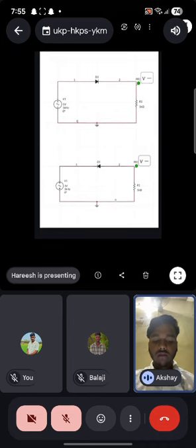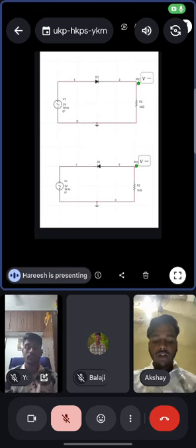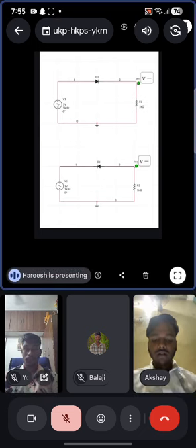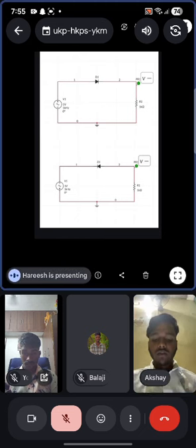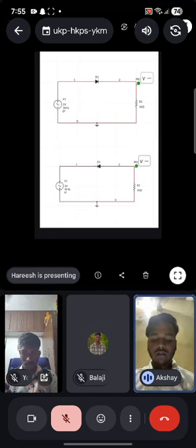Reverse bias is a condition where the p-type semiconductor of a diode is connected to the negative terminal of a voltage source and the n-type semiconductor is connected to the positive terminal. It allows engineers to design circuits that utilize diodes for rectification or signal processing while ensuring that undesired currents do not interfere, and solar cells use reverse bias to create a large depletion region, allowing them to efficiently detect light or convert light energy into electrical energy.